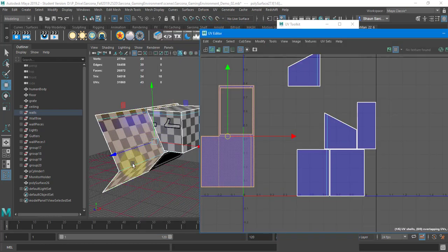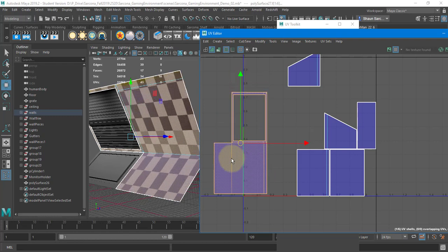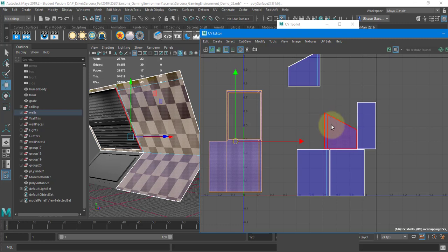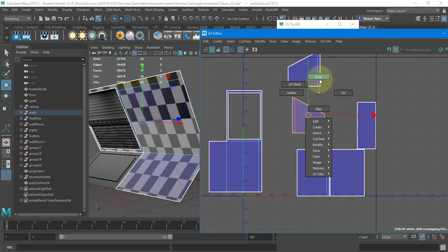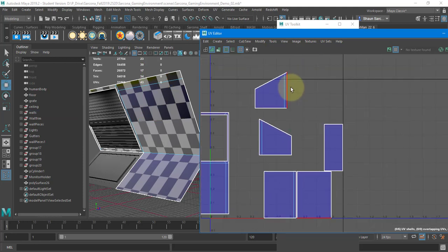So look at this outer piece. Our job is done with that one. That's already 1 solid piece. So we don't have to worry about that one at all. Let's look at this one, and we'll see if we can get this together. So I'm going to go to edge. And you'll see that as I move my mouse over each one of these edges, it'll actually highlight the shared edge, okay? Just like the tissue box, if I were to cut this edge here, even though I would have this face and that face, I have a shared edge that those 2 used to be part of. That's what I'm seeing. So I'm going to click on this edge.